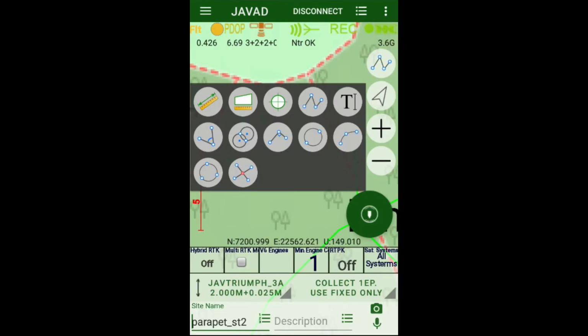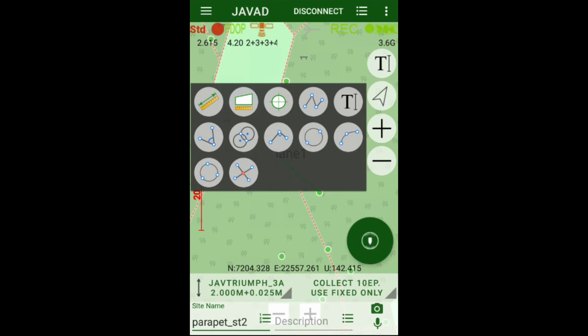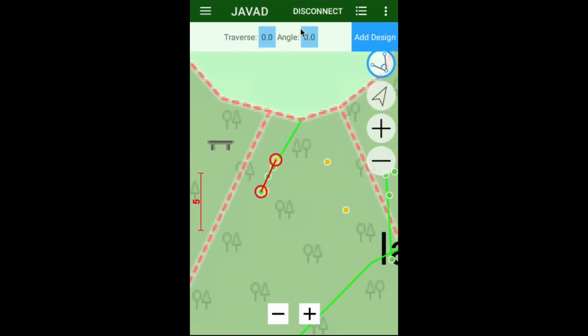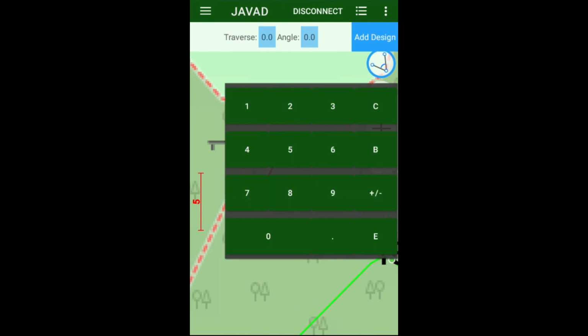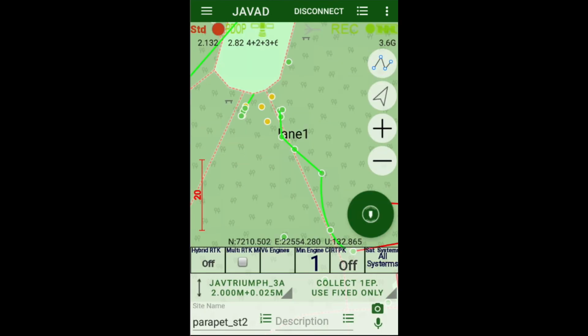Creation of graphic primitives allows you to complement the survey. Primitives such as line, arc, circle are supported. You can precisely define the parameters of the primitives using the bar at the top of the screen. So for a line it is possible to determine the length and angle, for a circle the center and radius. Drawn objects can be selected by clicking on them. To select a circle, click on its center.